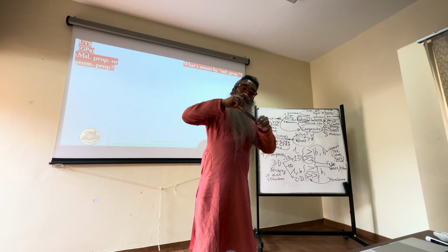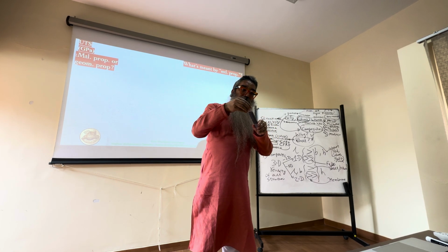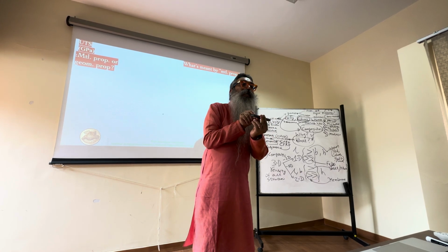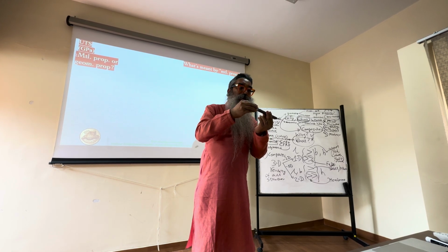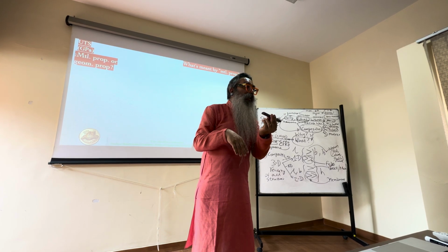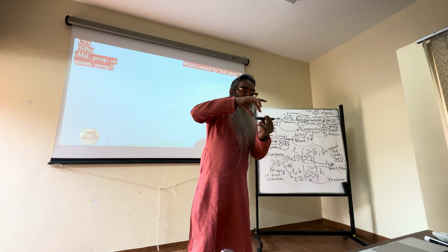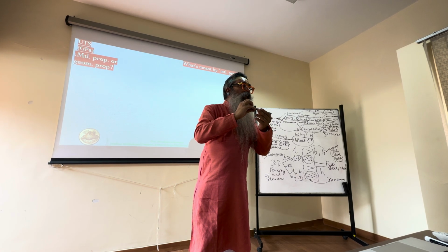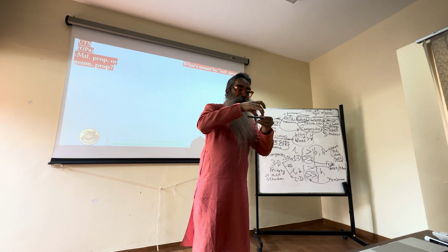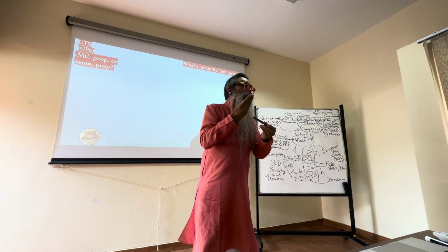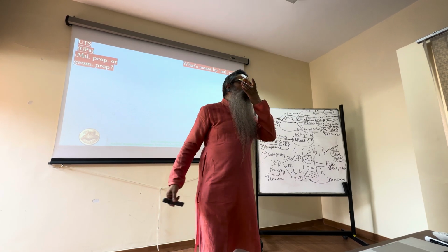So if this is one width, up to about one width, it will depend on exactly how I'm applying the load. But once you go to the interiors, it doesn't matter. The resultant is what matters. How you distribute that resultant does not matter, right? So you make it a dog bone shape so that it's much larger for the grips of the UTM to take hold, and in between in the dog bone there's a constant portion where you are actually measuring the stress and the strain.